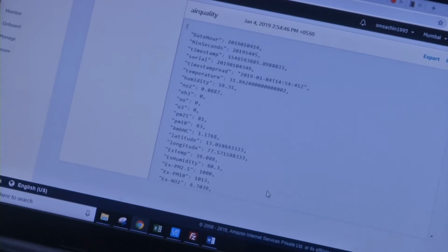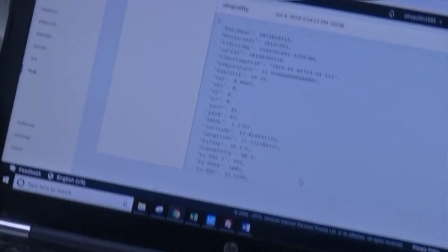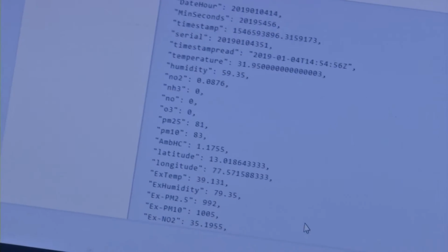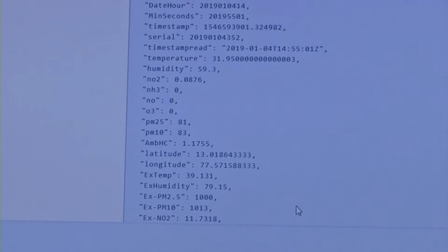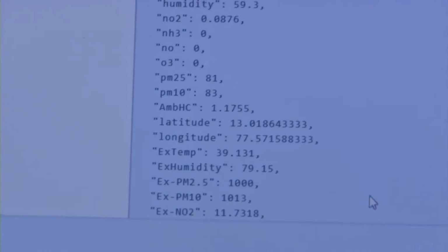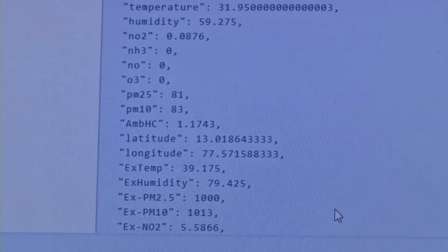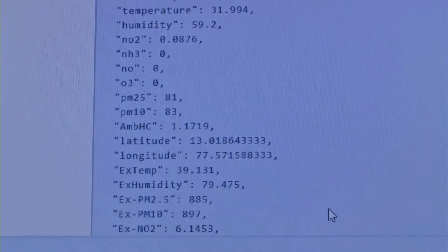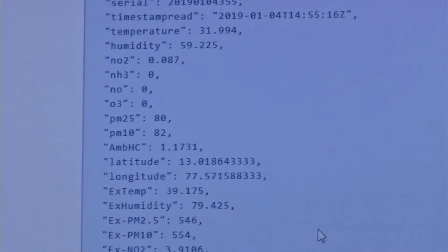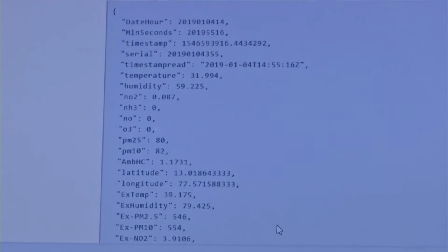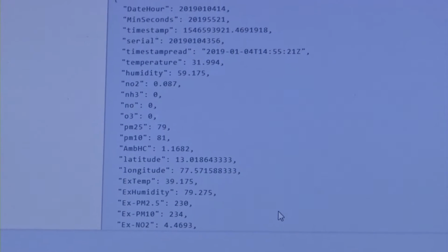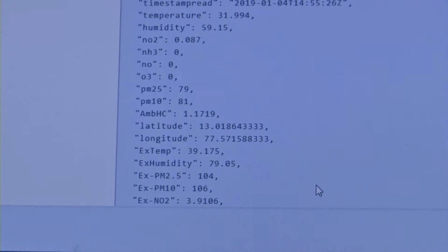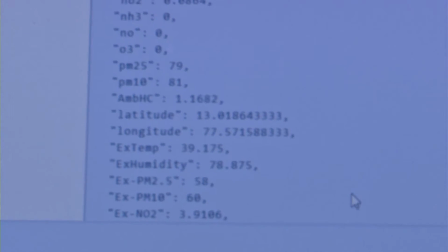Okay, now you can see that at very high acceleration, when the engine is rotating at very high speed, you get a very high value of particulate matter 2.5 as well as particulate matter 10. It has crossed absolutely dangerous levels, and this clearly indicates that one should drive based on the values that are being indicated on the dashboard, and it is more, I would say, air quality aware cars should come up, which essentially will allow you to keep the environment safe. You can see now values have come down because the vehicle is at standstill, and indeed it has fallen down